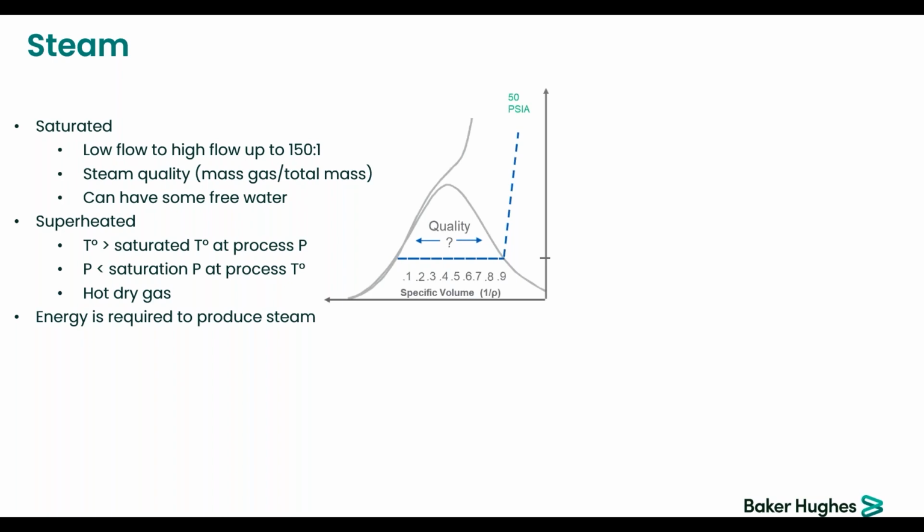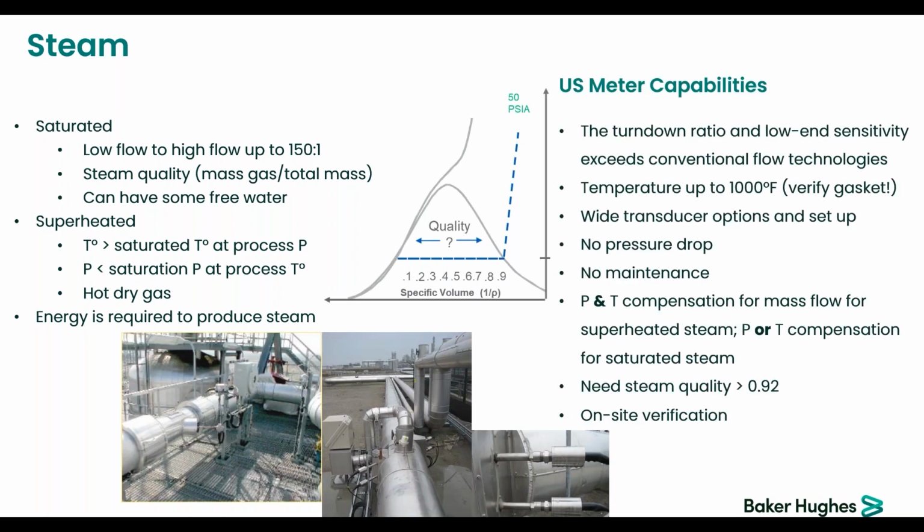If you have some risk, it's also wise to position the transducers and the nozzles on the horizontal axis if you have a horizontal line, so that it self-drains. If you are at a certain angle and one of the transducers and its nozzle is pointing downward, then it will collect all the condensate. You might end up with an acoustic short circuit that we don't want.